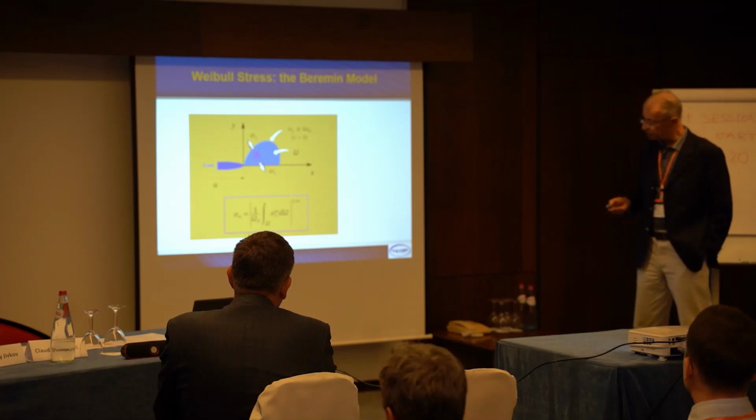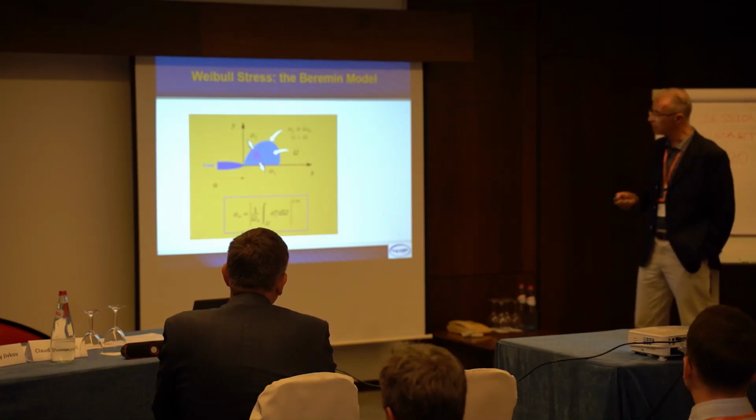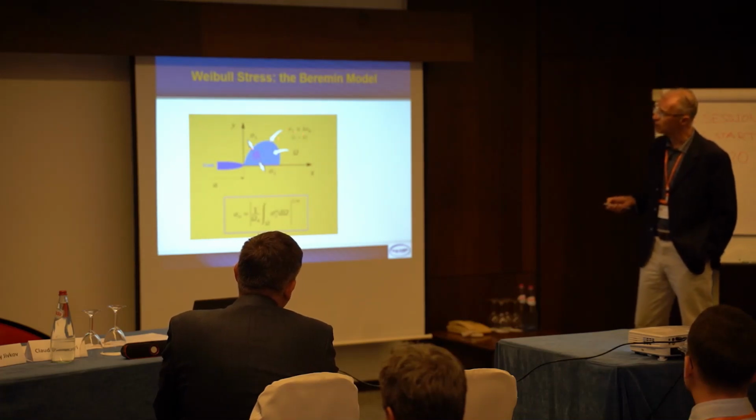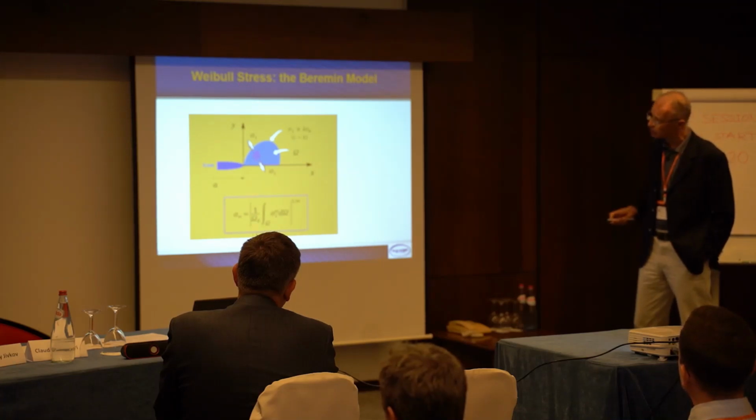What the Beremin group did many years ago was to coin this fracture stress concept, the Weibull stress, which can be seen as a probabilistic driving force.